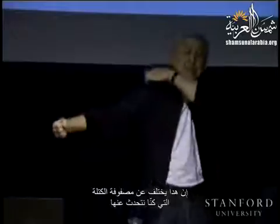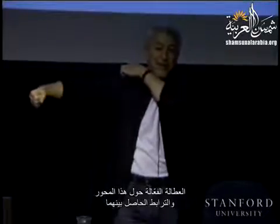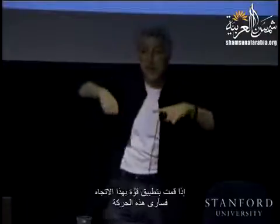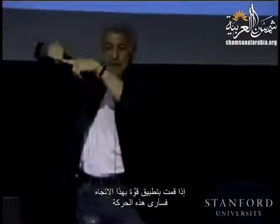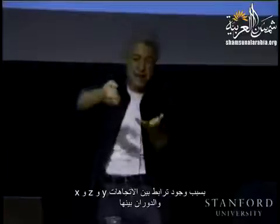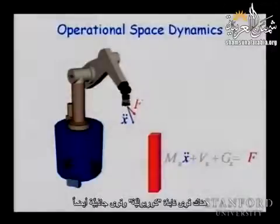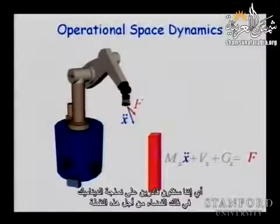This is different from the mass matrix that we were talking about, the inertial properties in joint space. The effective inertia about this axis is varying, the effective inertia about this axis, and the coupling between them. Now, if I push in this direction, I will see this motion, because there is coupling between the y direction and the z direction, and the x direction, and the rotation between them. But if I am able to model this, then, well, there are centrifugal, Coriolis, and gravity forces as well. So we are just going to be able to model the dynamics in that space for this point.